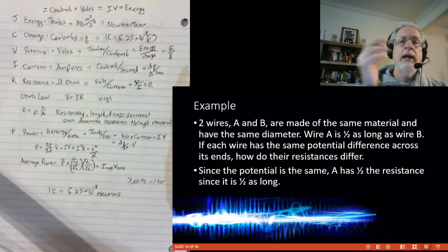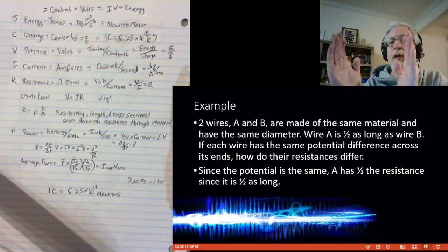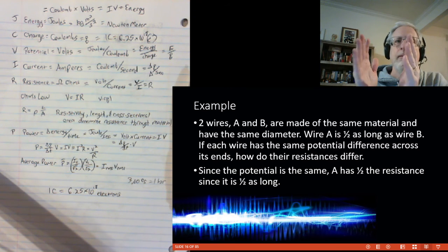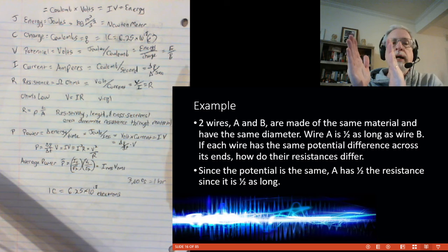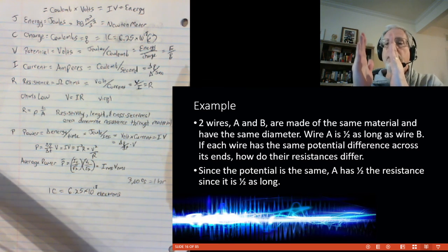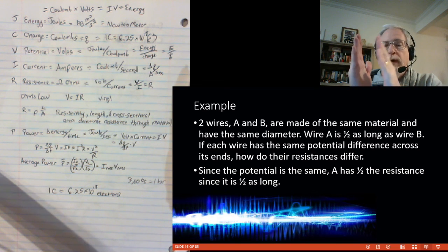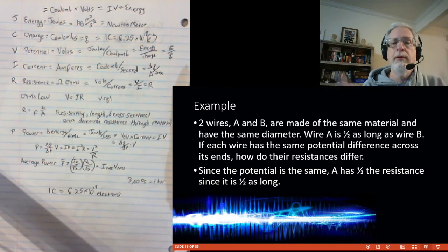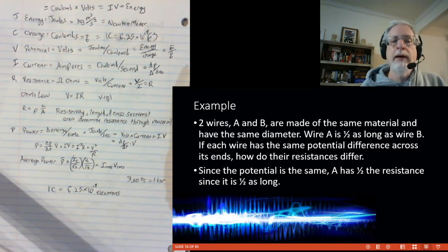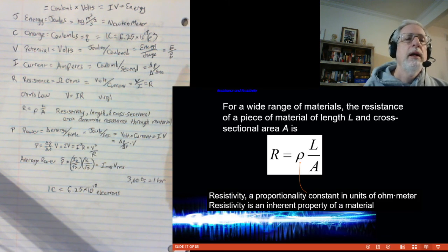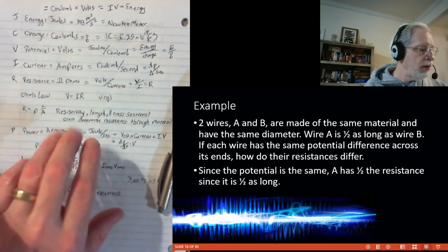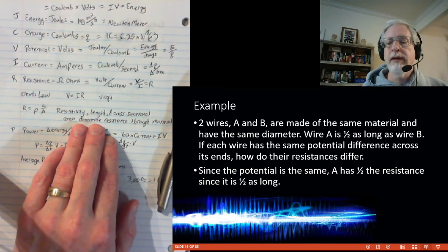It's just pure relational physics. If I have to go this far, it takes this much. There can only be this much resistance per piece of wire. And if I take two of these pieces of wire and put them together, it's going to double the resistance. So if I have half the wire, it's half the resistance. And that leads us to resistivity, which is where I will start the next video.